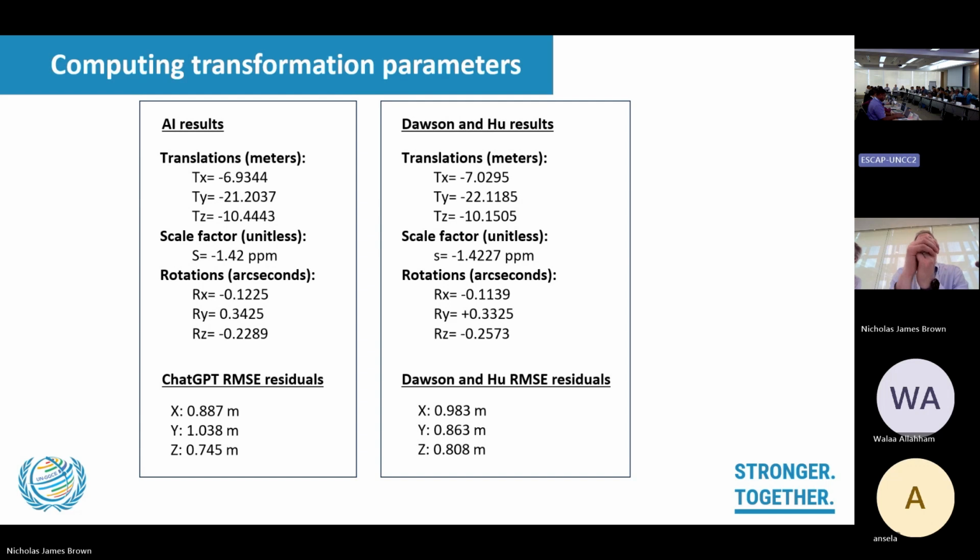And if you're having trouble, the reason could be, one, that the heights are causing more of a problem than we think, or two, that it's not a conformal transformation and there's deformation happening that's causing the bigger residuals. This is again why it's important to have more data, because then you can take data out from a specific region and ask, is it fitting well for that region but not this region? This is when you get into the art form. You can't just throw it all into the equation and assume you'll get the best result. You might need to study each of the individual areas slightly differently.